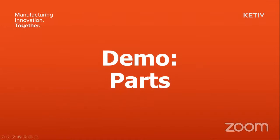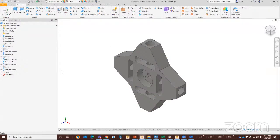And I'll start with an example I have here of a machine component. So the model states start to show up here in every single part file you have. Now this one's complete. I'm going to go ahead and get rid of this stuff and start over. Okay. So your master, you'll always have that. You can't get rid of that model state. It'll always be there. But as soon as you want to create a new one, you just right click and choose new.